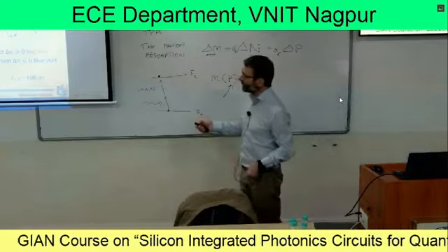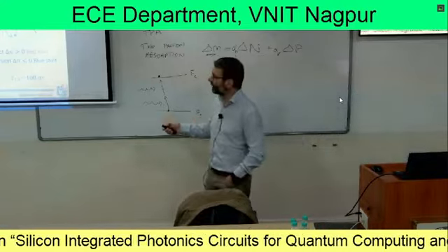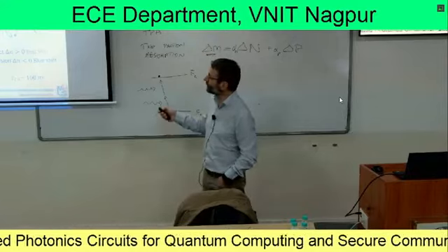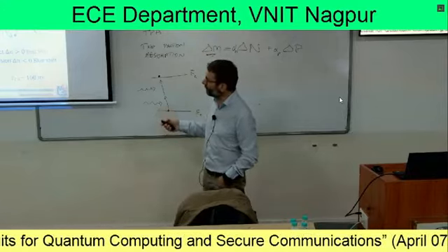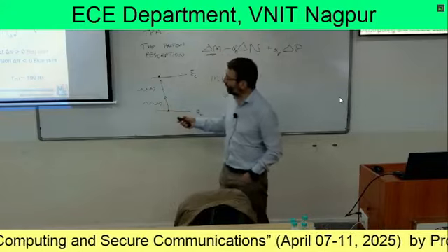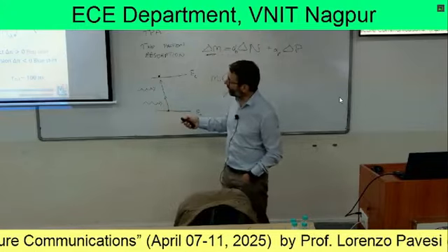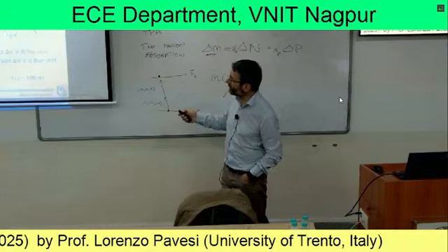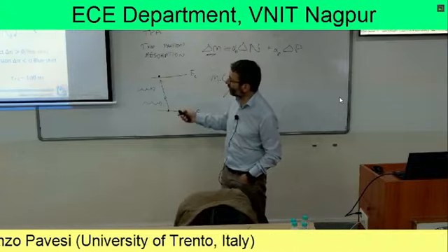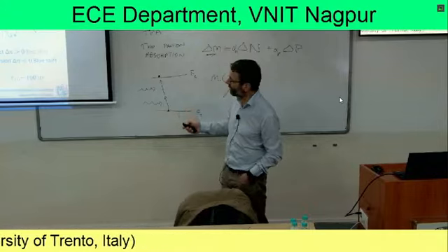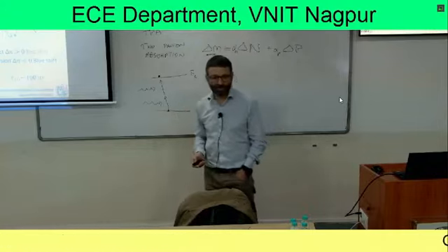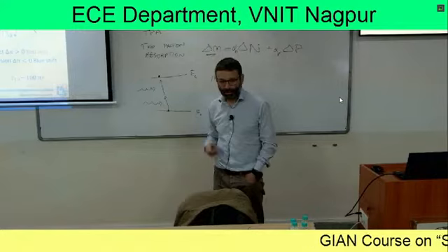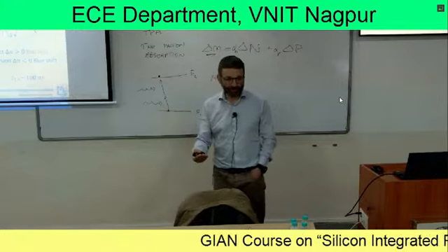And this is what is schematically shown here. You have the valence band, the conduction band, and then you have your input photon. A few of them can induce, by two-photon absorption, the generation of free electrons in the conduction band and free holes in the valence band. And this is the effect of the free carriers.